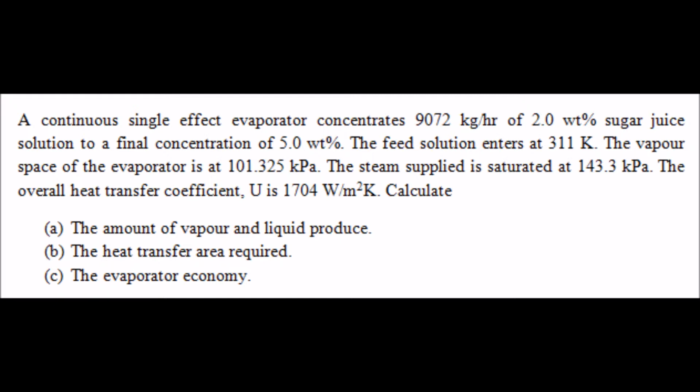The steam supplied is saturated at 143.3 kPa. The overall heat transfer coefficient is 1704 watt per meter square Kelvin. Calculate the amount of vapor and liquid produced, the heat transfer area required, and the evaporator economy.